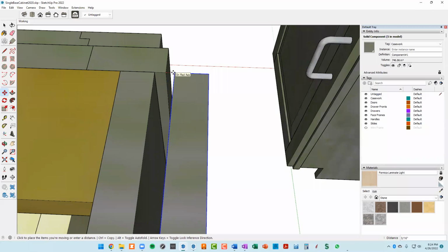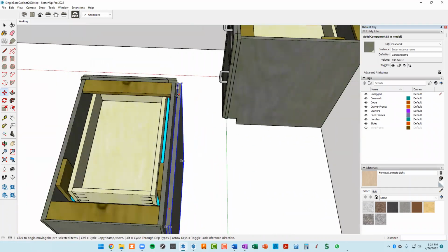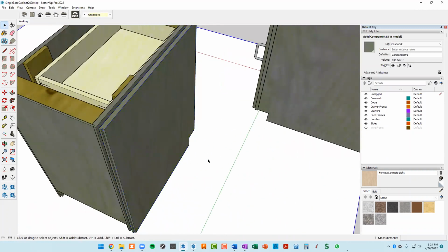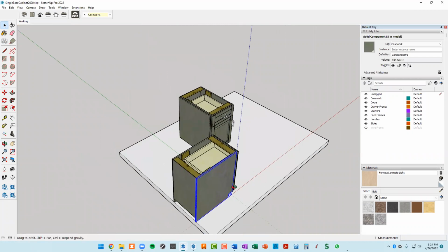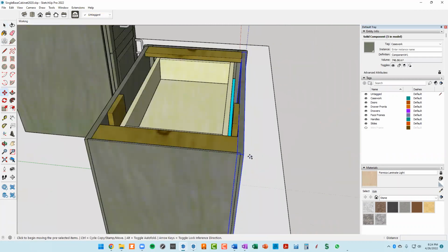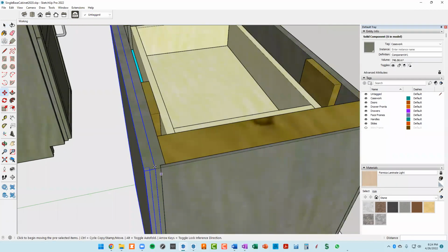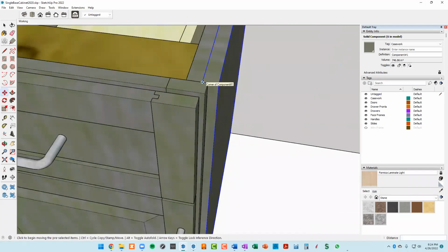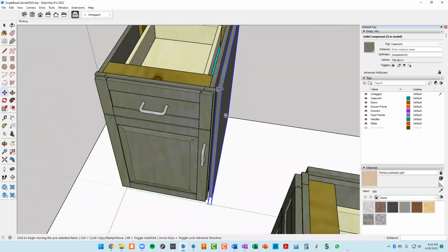And then I'm going to do my second click, my second move, and type in 1/4, because there's going to be another face frame that bridges that gap right there. Okay, and you can see that we've got this rabbet in the right spot now. So I'm going to do the same trick over here. I'm going to take this one and make a copy of it, move it along here. I'll just butt it up against the other side and then come around to the face frame side, and we're going to move this right to there and then another 1/4 inch beyond it and click a second time.